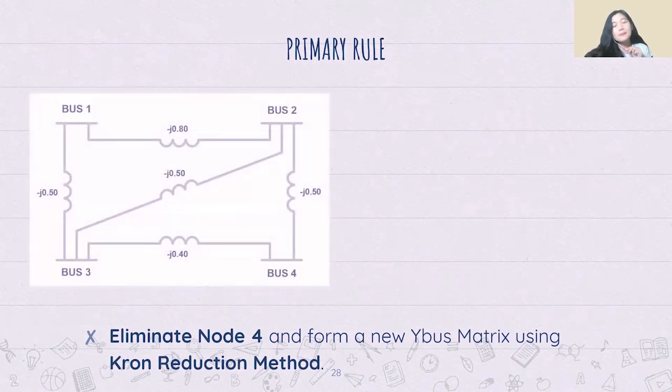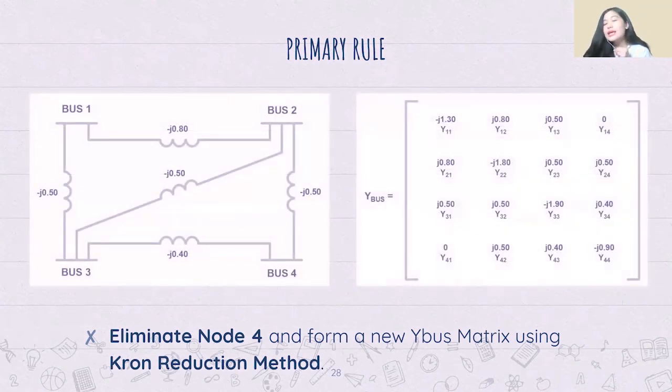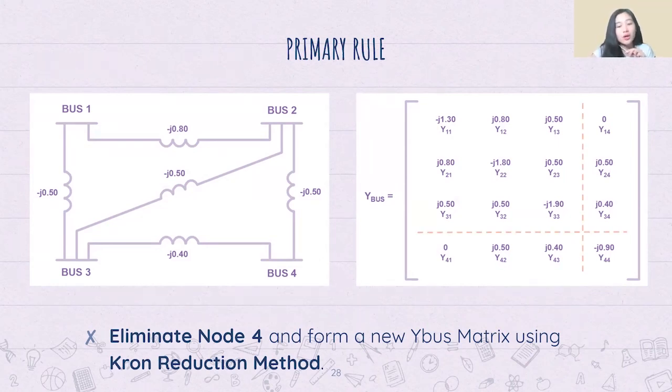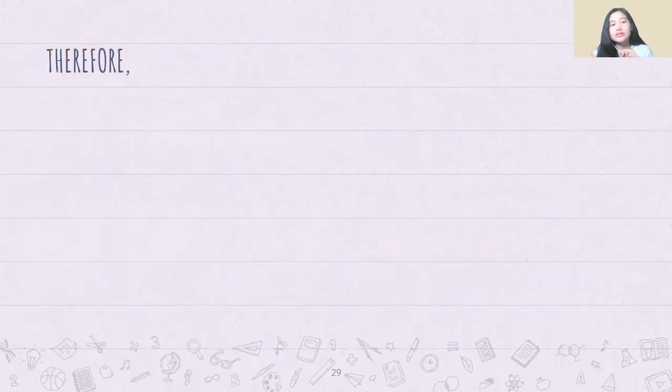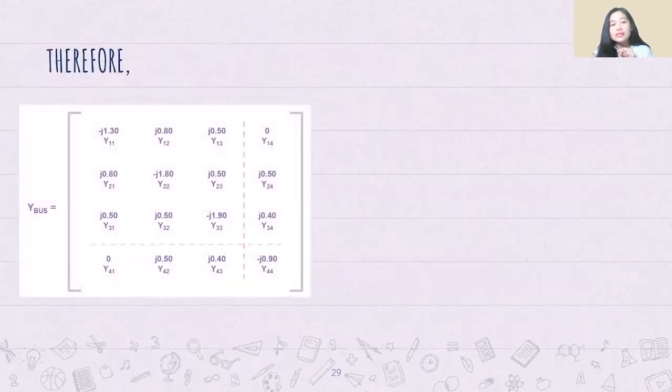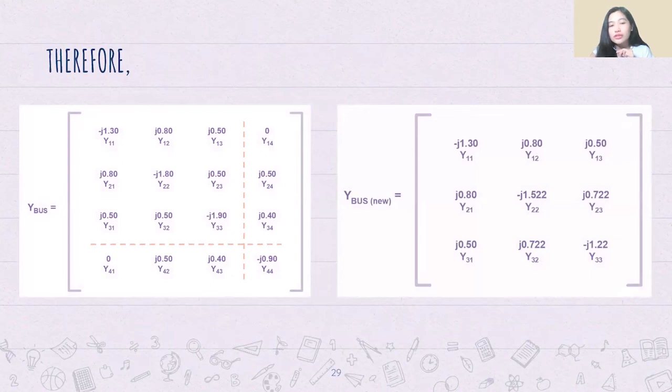So this is an example circuit that we used, and we have to have a prior knowledge of the Y-bus admittance matrix to be able to use the Kron reduction method, of course. Okay? Now, just by going back, let's just boil down that from our 4x4, we eliminated it, by means of the Kron reduction, we have reduced our 4x4 to our 3x3.